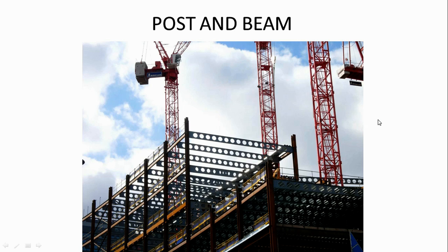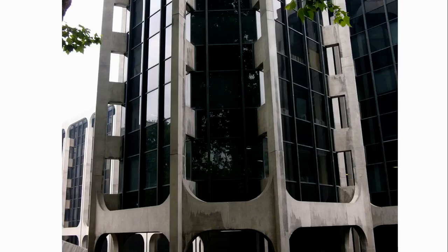Anyway, let's move on. So here's a simple post and beam structure. You'll note here the perforated beams doing the long spans. That's what, 8-10 meters probably. You'll note these are not I sections, are they? But they're square section columns carrying the loads to ground.